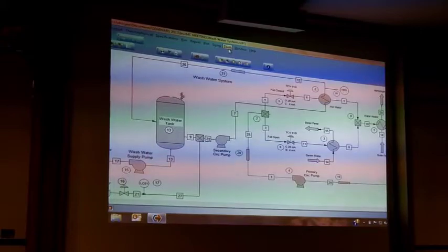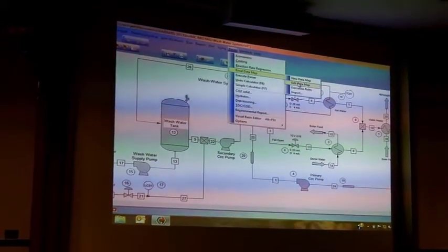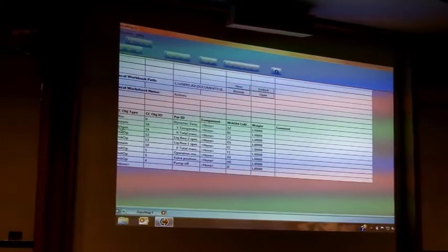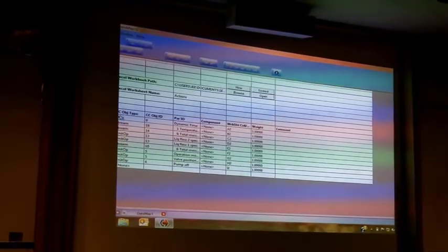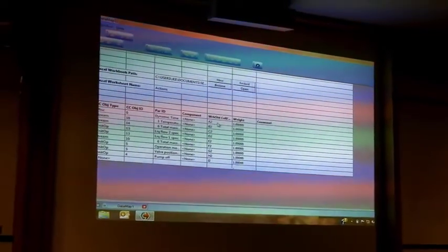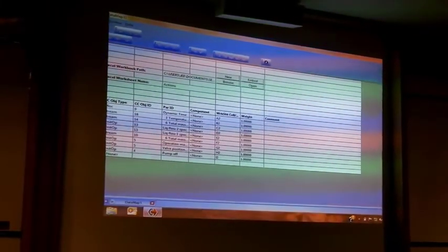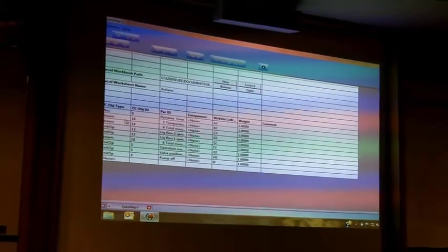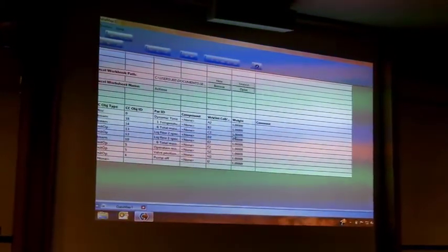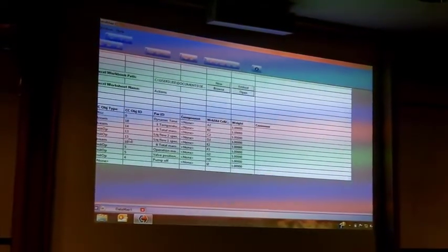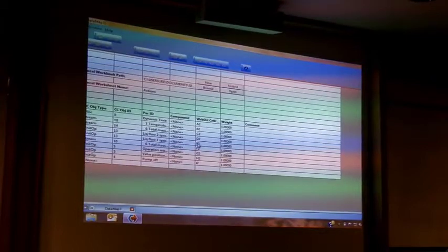And it's connected to a spreadsheet, and you can see what I'm doing in here. I'm sending the dynamic time into cell A2, and then I'm sending these values back to ChemCAD. So stream 18 temperatures going into cell B2, stream 14 C2, unit up liquid flow spec.